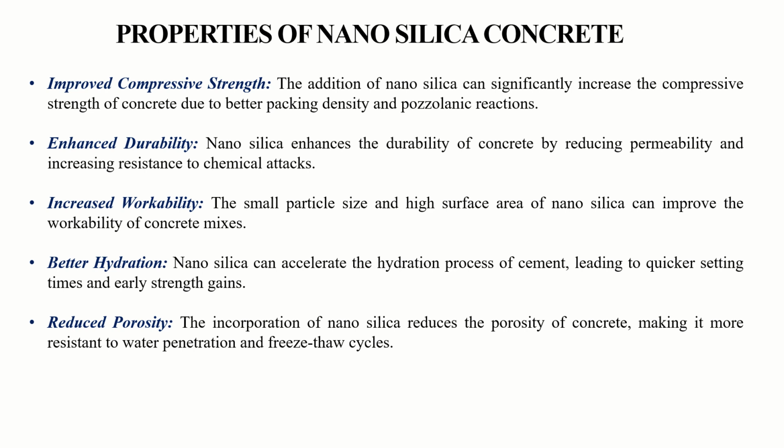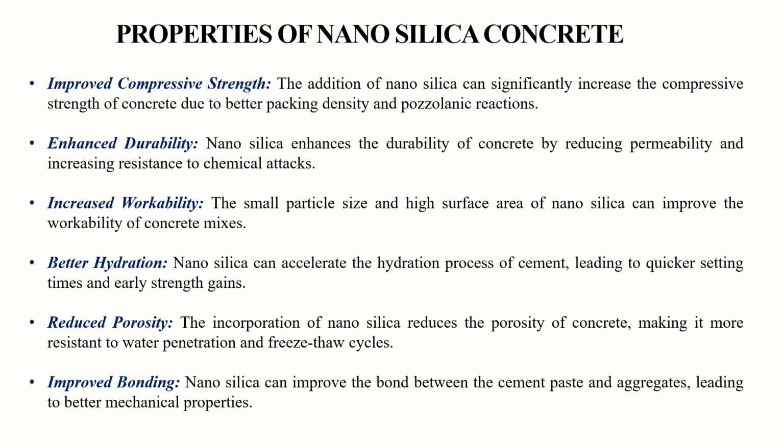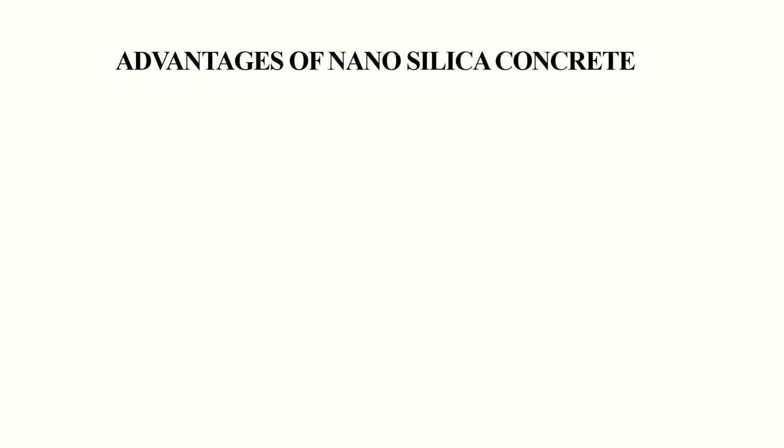Thereby, it reduces the porosity because of the very fine particles, and also it increases the resistance to water penetration and also freeze and thaw cycles. And coming to improved bonding, nanosilica can improve the bond between the paste and the aggregate. It would enhance your ITZ, therefore resulting in better mechanical properties.